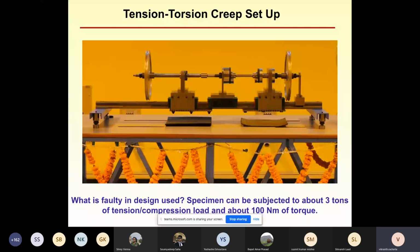So, what was the issue? The issue was that when we are applying tension torsion on this vertical column over here, we are basically generating a force of 3 tons, or 30 kilonewton force. Now, this 30 kilonewton force is generating a moment of 30 kilonewtons multiplied by about 0.2 meters, which was a huge amount of moment. 6,000 Newton meters of moment was getting generated on the rail.